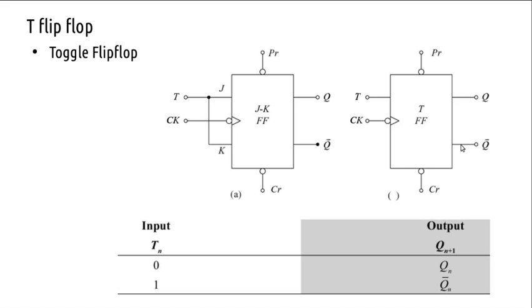So this is the logic symbol for the T flip flop. I doubt you will get the T flip flop directly. We make the T flip flop using JK itself. If J and K are tied together and given high, it becomes a T flip flop, a toggle flip flop. That becomes a toggle flip flop, right? Then finally we have, so just draw it.